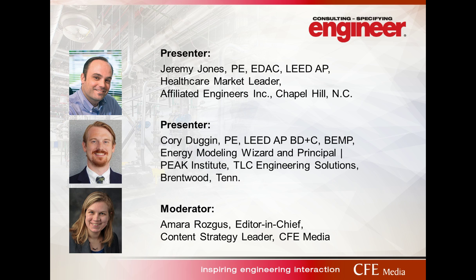Sure. So this is an example of where VRF systems are not specifically not allowed, in the same way that chilled beams aren't specifically not allowed in spaces that are not allowed to have local recirculation. But it is difficult to meet that requirement with a VRF system. I wouldn't say that it's completely impossible.